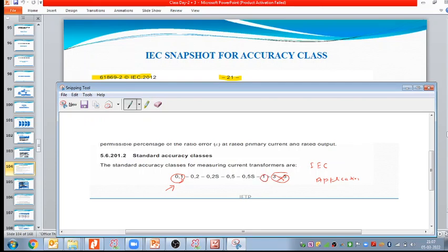And when it comes to low voltage, when it comes to LT, low voltage I'm telling means 220 volt, 415 volt or 400 volt. This is my low voltage range. For medium voltage, class 1 CT we can use. For LT, for sure, class 1 CT we use, right?